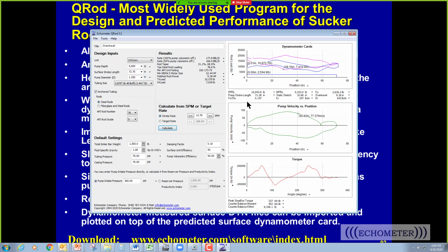Thanks. Okay, Travis is having problems. He has a lot of wells that only make 5 to 10 barrels a day, but it's impossible to get the pump capacity that low due to their pumping unit size. So I'm assuming he has a large stroke length in those units. Since we do not have electricity for a pump off controller, how can we get good pump fillage?